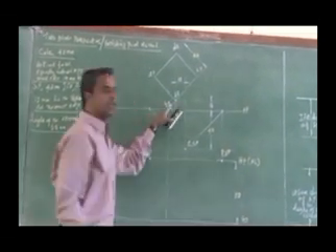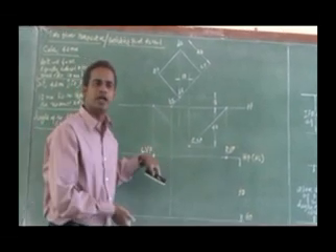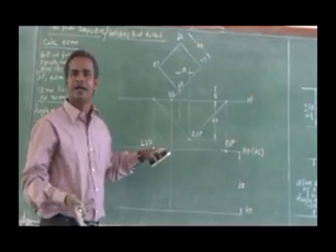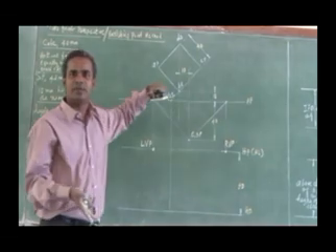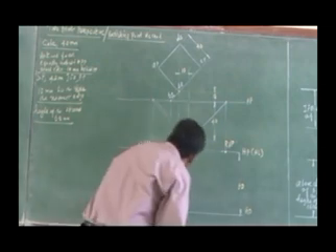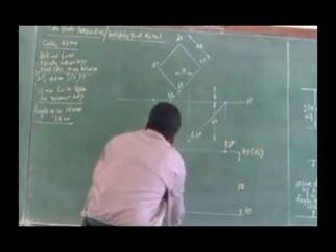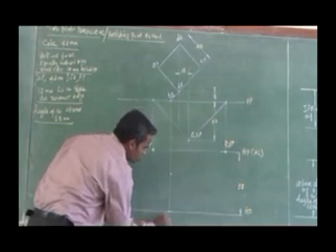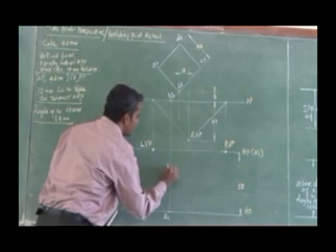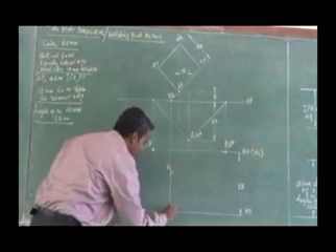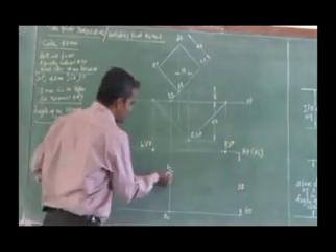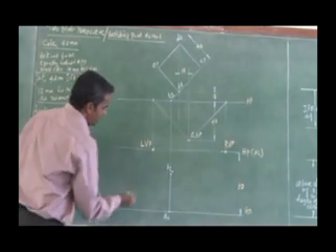Now conveniently, the B2 Q2 perspective I can draw to which height? 40 mm. That is the true height. The cube's height is 40 mm, the side is 40 mm. So the B2 Q2 perspective I can obtain for exactly 40 mm. So this is going to be my B2, this is going to be my Q2. This is not the actual edge of the cube. This is just the 40 mm true height I am obtaining.